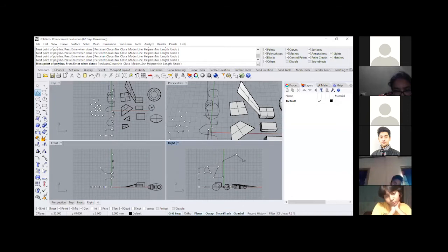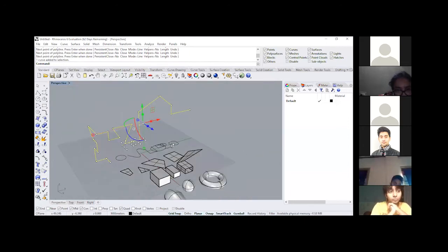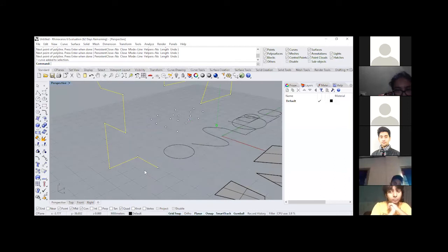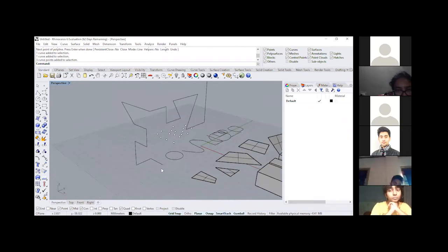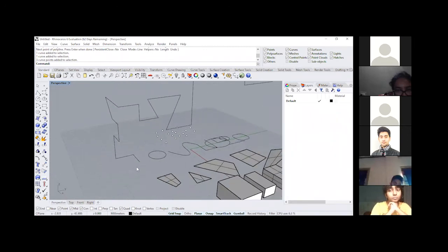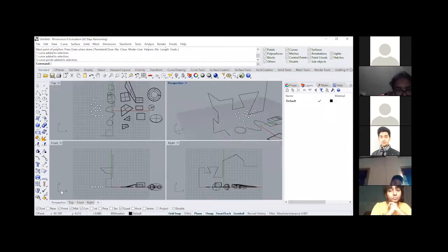All right, you can go ahead and draw out anything. And now I'm pressing enter to end the command sequence. Now I want you guys to just take a look at this entire polyline section. The first section, we drew it on the top viewport, wherein you can see these 3 other points. Correct? So you have it all on the base XY plane. And then we started drawing it on the front viewport, which had the base construction plane of XZ.